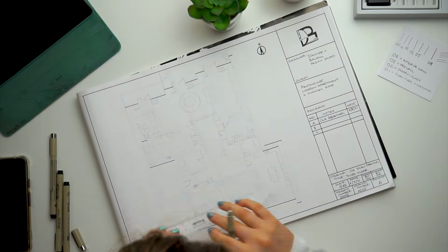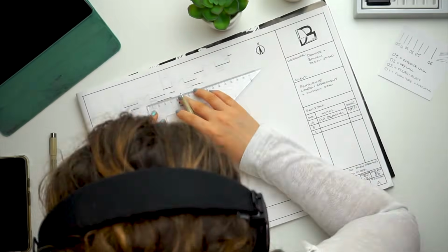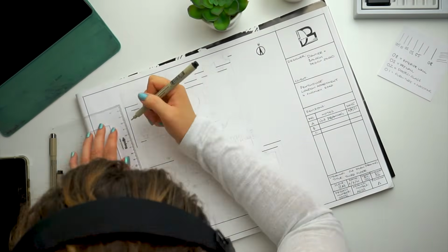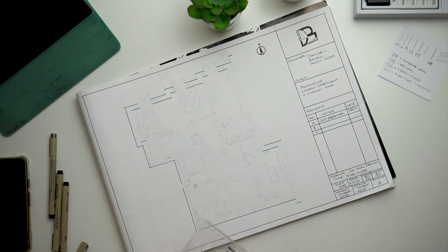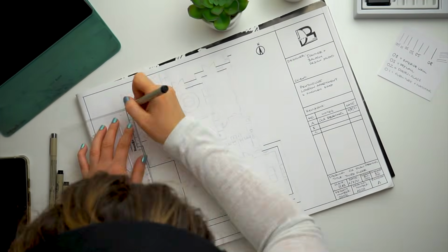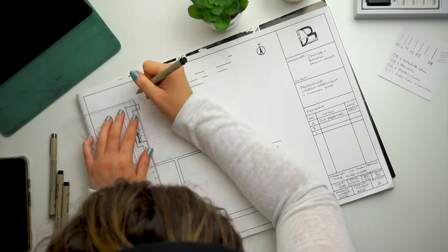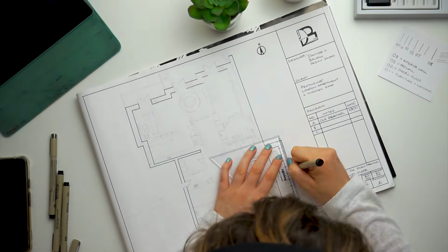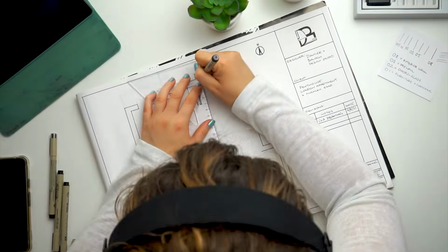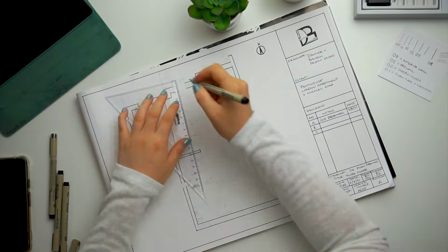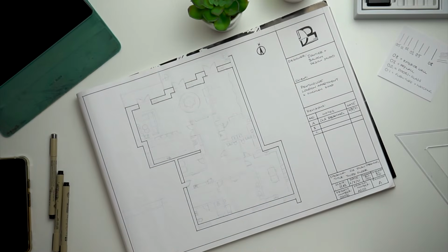So now that I've established my line hierarchy and which pen sizes will represent what drawing features, I'm going to stick to it and complete the floor plan in pen. I always start with the exterior walls, which are the thick lines, and work my way down, so I'll do the interior drywall and balcony railing with a slightly thinner pen nib, then so on and so forth until the furniture.